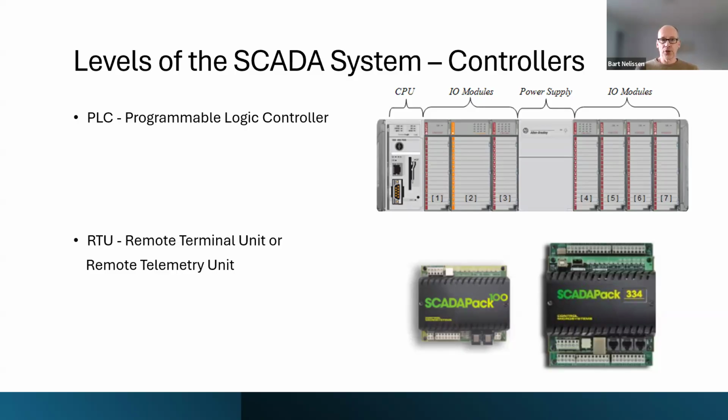And then there is a module, a component of a PLC that is called a power supply, which is the one that would generate enough and proper power to power up outputs. So when we, for example, say the PLC turns a light on, then we need to provide power for that light, and that comes from the power supply. So those are the three different components of a PLC: the central processing unit, which is the brains, the modules for all the inputs and outputs, and the power supply.